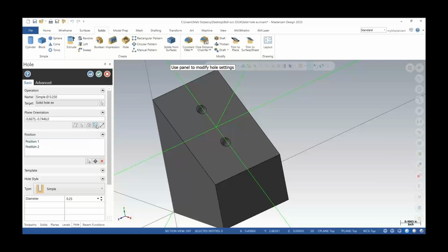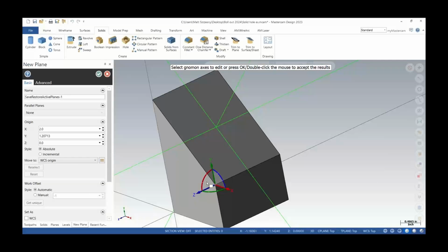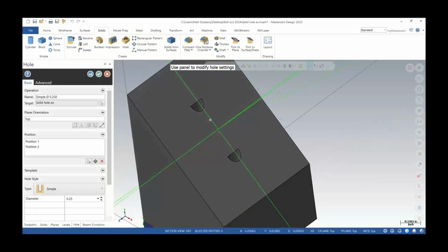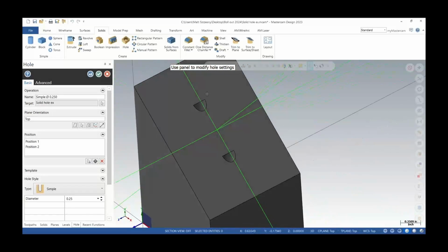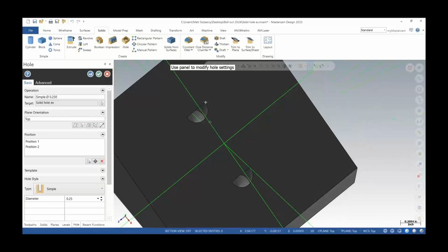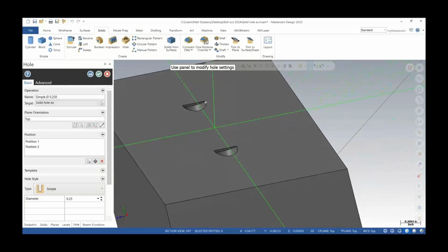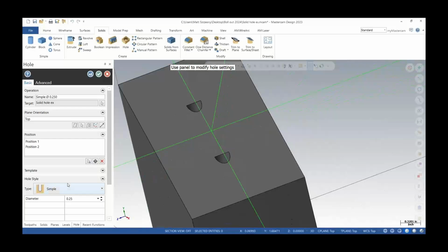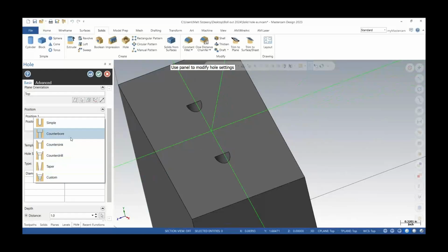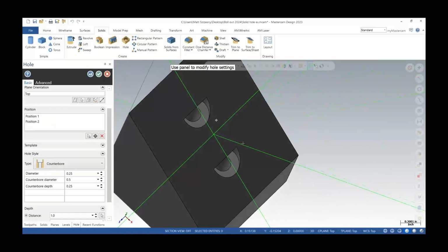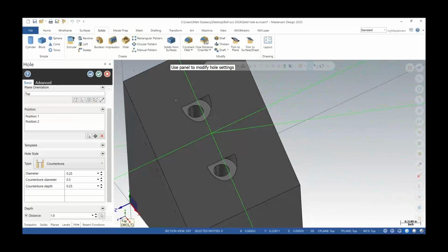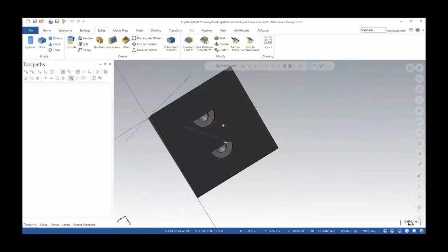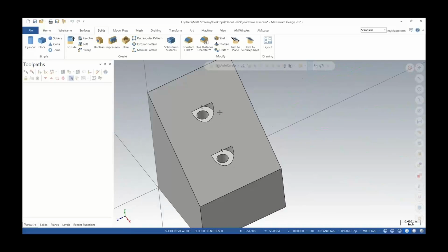And it looks fine now, but if I rotate the plane on where those are sitting, we can see the issue from perpendicular view from where that ramp location is. We're getting basically a cut hole, it's half a hole, not really our desired outcome. If I switch this to a counterbore itself, it's a pretty hard part to machine if you ask me. So these are kind of the options you may have seen in 23.